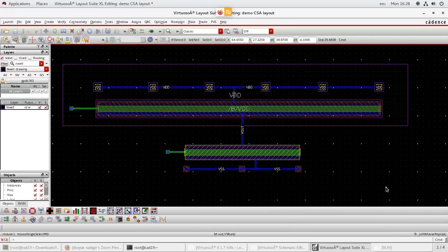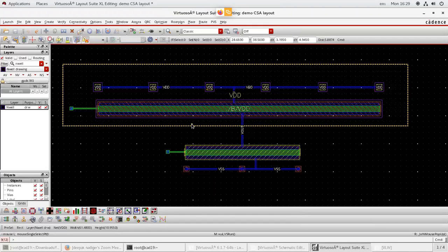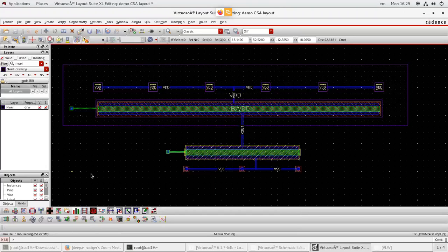By virtue of their nature, all materials have some resistance. When you have two metals and in between you have some dielectric, obviously some capacitance is formed. I think people have studied the capacitances formed in MOSFETs. So because of the properties of materials, some parasitic resistances and capacitances are formed. For this reason, we can extract the parasitic capacitance and resistance of this design.